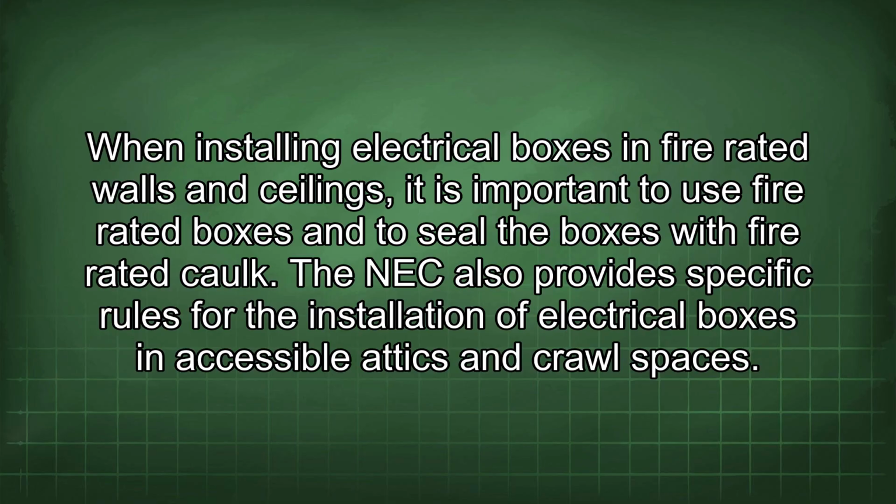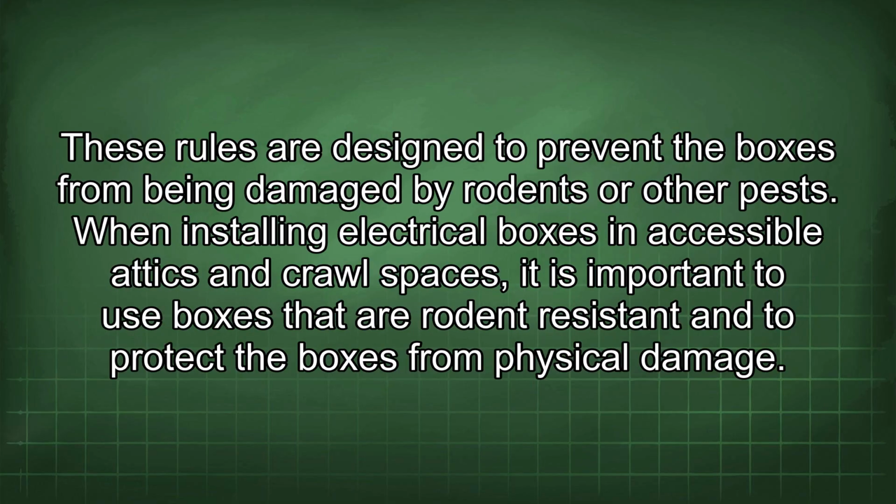The NEC also provides specific rules for the installation of electrical boxes in accessible attics and crawl spaces. These rules are designed to prevent the boxes from being damaged by rodents or other pests. When installing electrical boxes in accessible attics and crawl spaces, it is important to use boxes that are rodent resistant and to protect the boxes from physical damage.